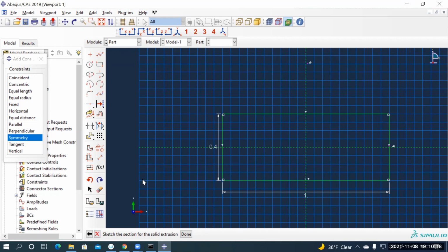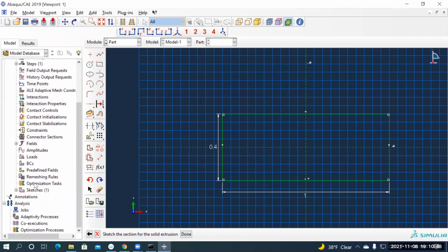Okay, so before we say done, we'll save this sketch and we'll bring it back again on a different datum plane. The way to save the sketch is, you would see the floppy disk icon. This is the floppy disk icon, save sketch as. Click on save sketch as, save it as sketch 1. And when you enter, it would have gone. In the tree, it says sketch 1. That's where it has gone. We'll go and bring it in when we need it. It's right now there at the bottom of the tree.